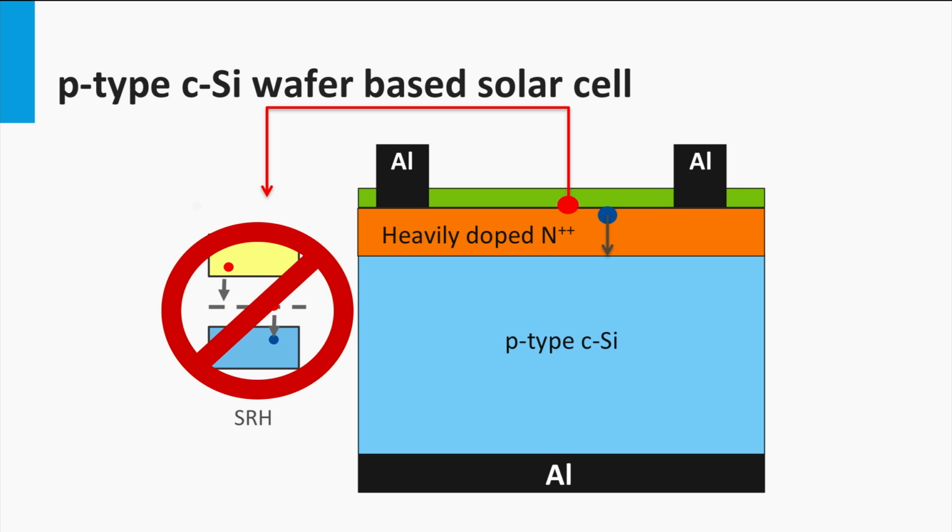In this case, the hole is indicated by the blue dot. Note that many charge carriers are generated by the bluish photons close to the surface. To utilize these light-excited minority charge carriers, the diffusion length of the holes has to be large enough to reach the depletion zone at the p-n junction, as indicated by the blue arrow.